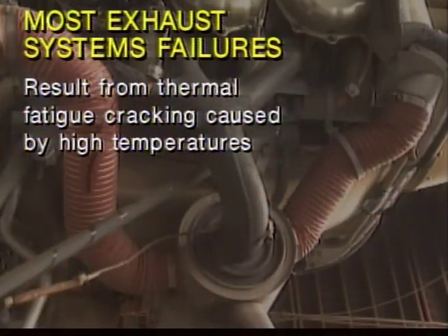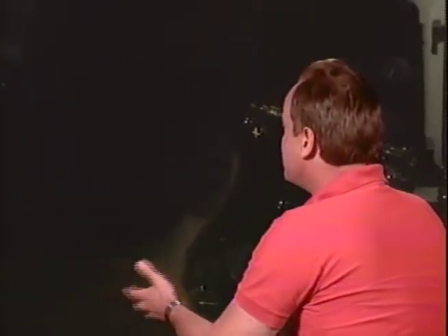And so if you're flying at night, you have this insidious thing happen to you, like the back of the head sneaks up on you, you could be having carbon monoxide poisoning. You may be not flying at night at all. Your vision just gotten very, very bad because of carbon monoxide poisoning. All right, so if you have an undetected exhaust system leak in a reciprocating powered airplane, it could lead to pilot incapacitation. And that's from carbon monoxide poisoning or gas entering the cabin.